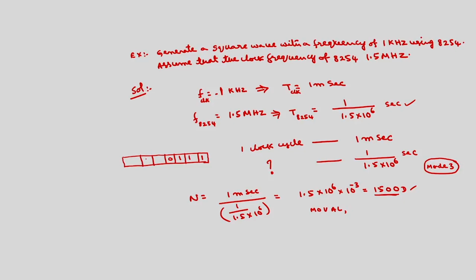So, this will be 1 1. 0 0 is latching, 0 1 is lower order 8 bits, 1 0 is higher order 8 bits, 1 1 is 16 bit. In that, first it will load the lower order 8 bits, then the higher order 8 bits, and these are the select counter bits. I can use any counter. Okay. If I use say counter 0, 0 0, this will be 37H.